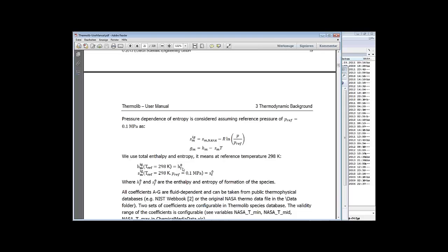So that means the enthalpy of combustion of coal is a result of this absolute enthalpy, because it already includes the chemical portion and the latent heat or the sensible heat. As soon as you involve any species in a chemical reaction, the enthalpy balance of the chemical reactor will be: input enthalpy is equal to output enthalpy.